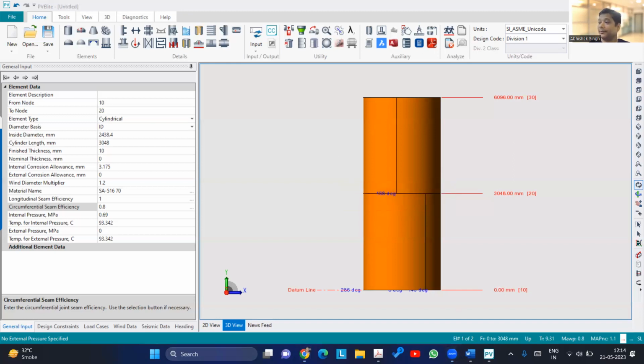Okay. If I just draw that, there will be a heating rate. Then there will be a holding temperature where you'll hold that. Then you'll cool down. You have to maintain a certain heating rate and a certain holding time. That depends upon thickness. Heating rate also depends upon thickness, and the cooling rate also depends upon thickness. So this is one cycle. Okay. So now the question is, how many cycles should we have?